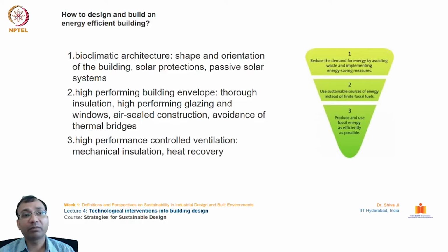The second, high performing building envelope, thorough insulation should be there, so as to minimize the losses. High performing glazing and windows, air sealed construction, avoidance of thermal bridges. The third one, high performance controlled ventilation, mechanical ventilation, heat recovery.